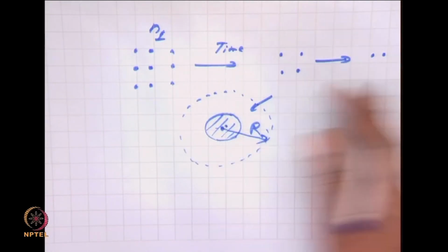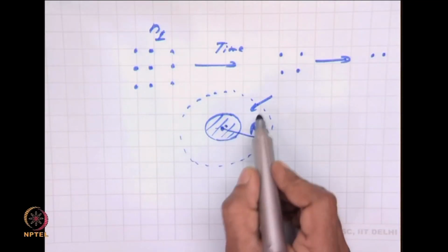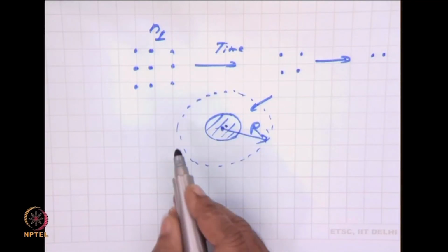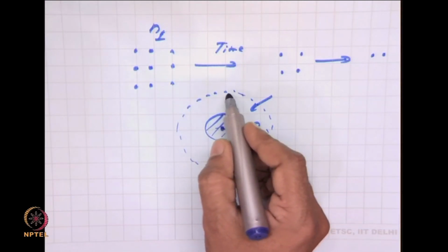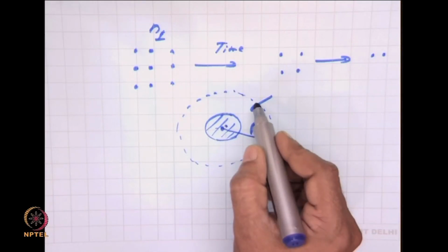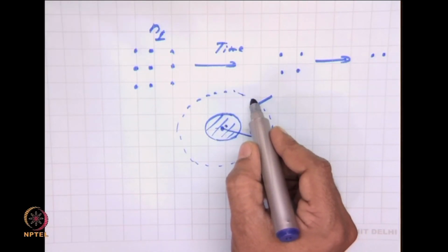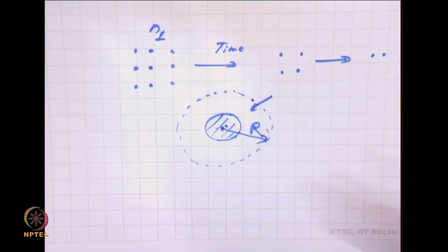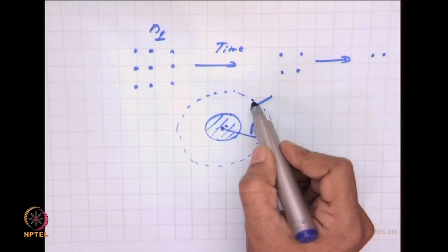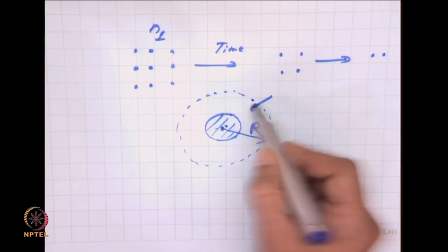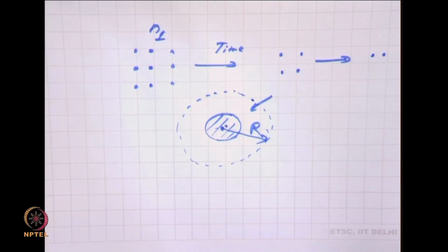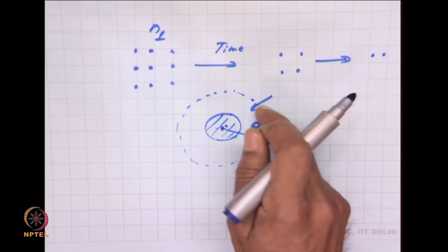Around the sphere of coagulation till infinity you have all the particles. If this sphere is acting as something which is able to make particles vanish, we could say the number concentration of particles at this boundary will always be 0. Anything which comes to that point will get immediately removed from the system. So, the free primary particles number concentration on this spherical envelope will be 0. Far away it will be whatever the initial concentration is. Supposing the initial concentration is N0, that will be N10, the initial concentration far away. Here the concentration is 0.